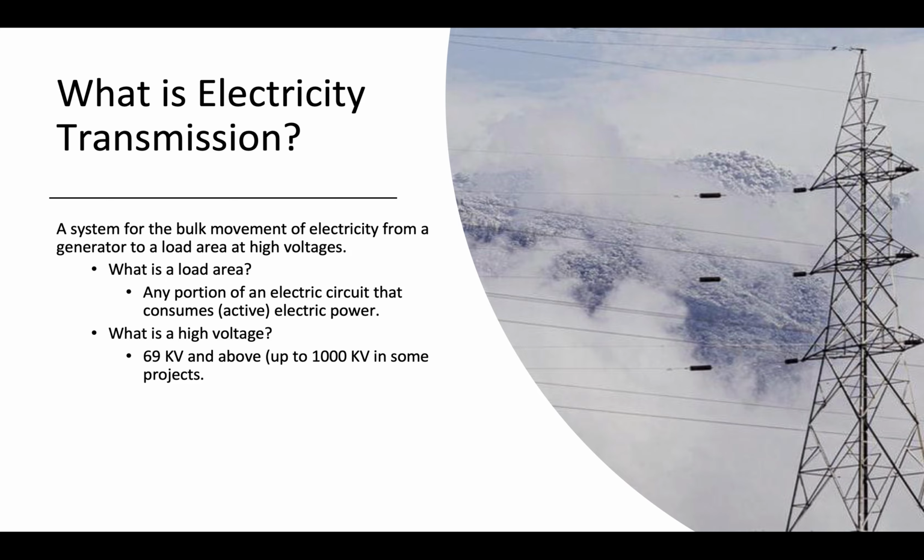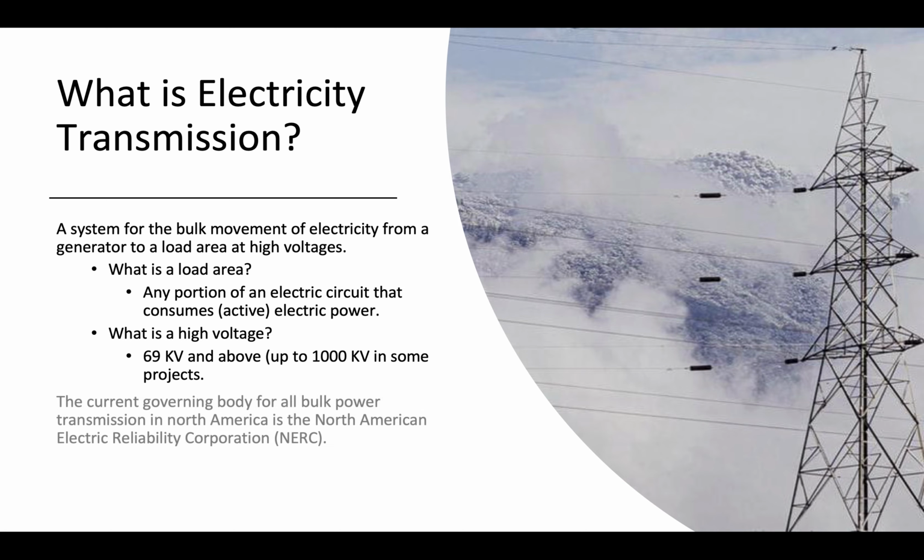Once electricity is close to its point of use, a power substation is built where the voltage can be reduced through step-down transformers to distribution voltages below around 69 kilovolts. Voltage is then stepped down again at its final destination, usually at pad-mounted transformers or pole-mounted transformers, where it can be reduced down to 120 to 240 volts, which is used in a lot of households.